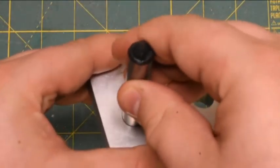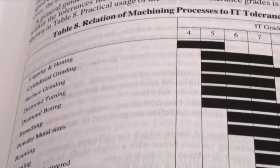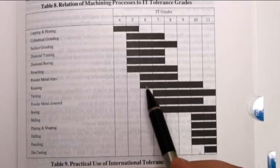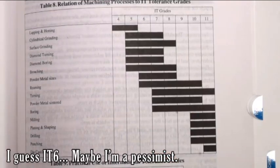The numbers themselves are actually determined by the IT system, the International Tolerance System. Every manufacturing process can be statistically analyzed and an IT number can be determined. This means that if I'm reaming a hole, I can look up the reaming process and see that at best I can achieve about an IT7. So I can't specify an H5 or a G5 hole if it's going to be reamed.